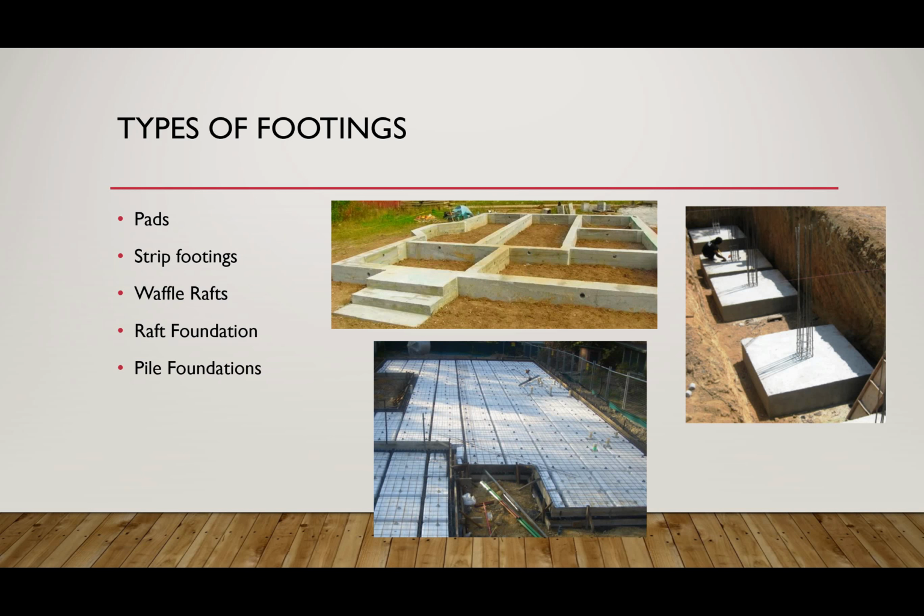We've got different types of footings. We've got pad footings, which are over here, which are used to locate columns. So we have a column here, and what the pad footing does is just spreads out the weight or the load over a greater area. If you think about a pen and you try to put a pen through a bit of paper, it's a lot easier than if you try to do it with a texta.